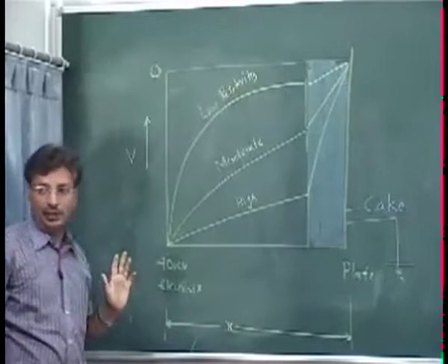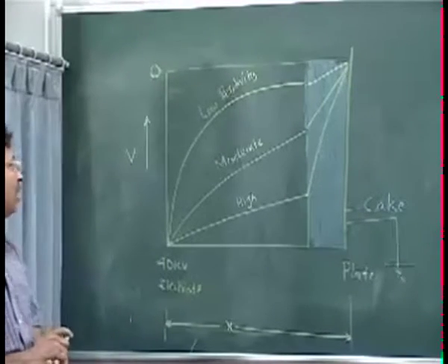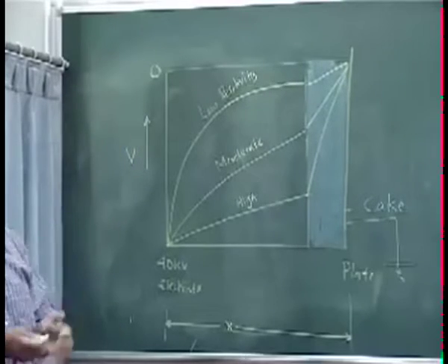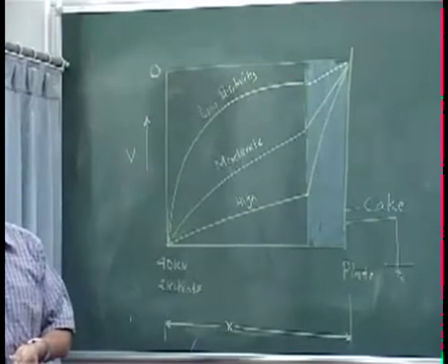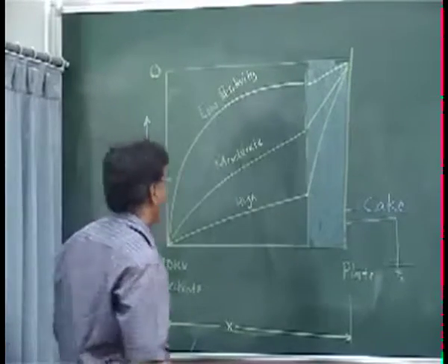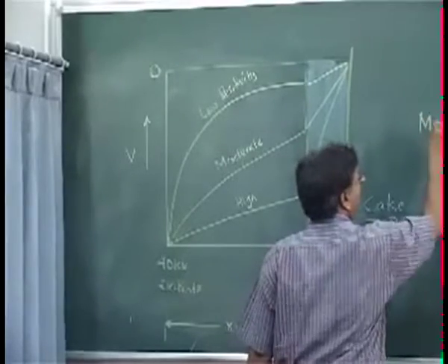In your opinion, which kind of dust will I collect best? The higher one? That is generally what people feel, but this is not correct. The moderate resistivity is best, and I'll give you the idea about what this number really is.